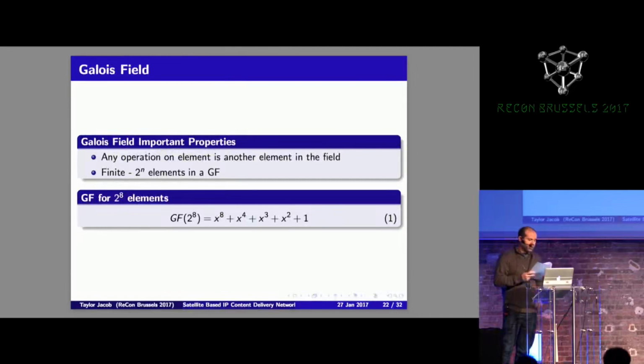So a key part of the forward error correction is Galois field arithmetic. A Galois field has 2 important properties. The first is that it's a set of integers where math operations, addition, subtraction, multiplication, or division between the integers, result in another integer in the set. The second property is that the field is finite. The FEC scheme that I'm speaking of, and in fact most others, are a set of algebraic equations that are used to calculate the missing elements from the others.